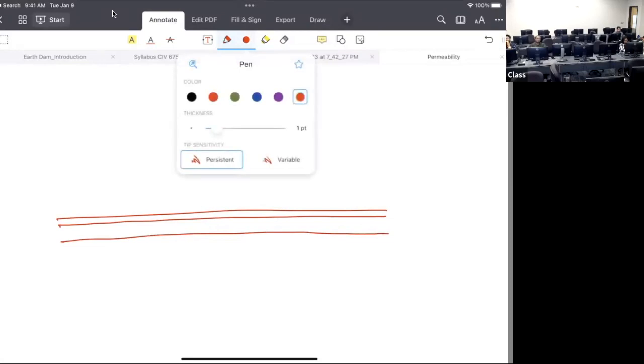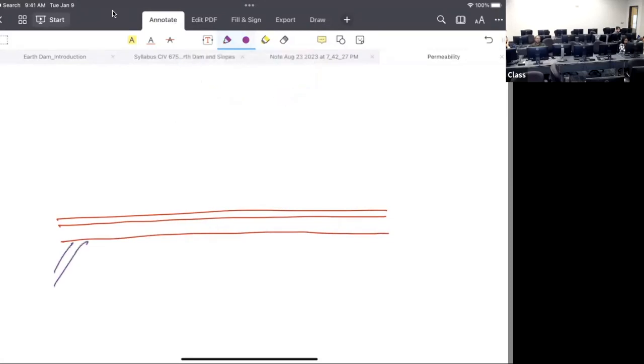So let's say this area is substrate. And in Mississippi, the rule, I think in most cases, is an undercut. Wherever you have the pavement, you cut it, excavate the top 3 feet, replace it, bring new materials, and then build the road.